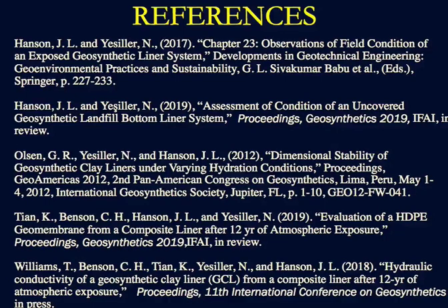That could be something to consider in addition, as one more dimension of prevention in terms of preventing the separation of the panels. But I think the construction QA/QC would be most important. Just assure that on the order of 1 foot of sand, 300 millimeters of sand, is placed or more. And that should generally take care of the diurnal cycling.